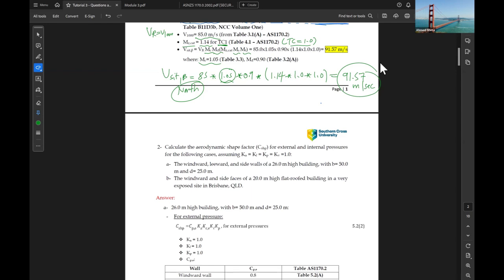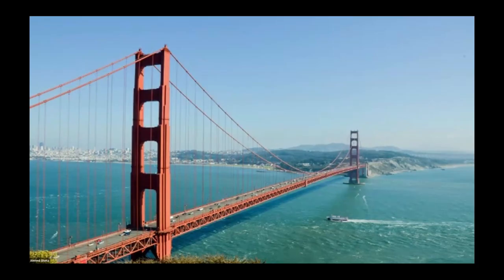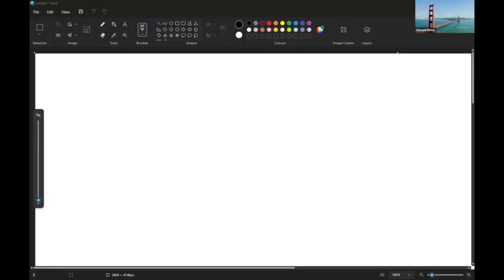When calculating the load in the assignment, trying to calculate the load on the roof girder, when we're calculating the uniformly distributed load for a girder, do we include the self-weight of the girder? Because I couldn't see the self-weight being included in the formula in the example from last week. Not sure if that's very clear or not.